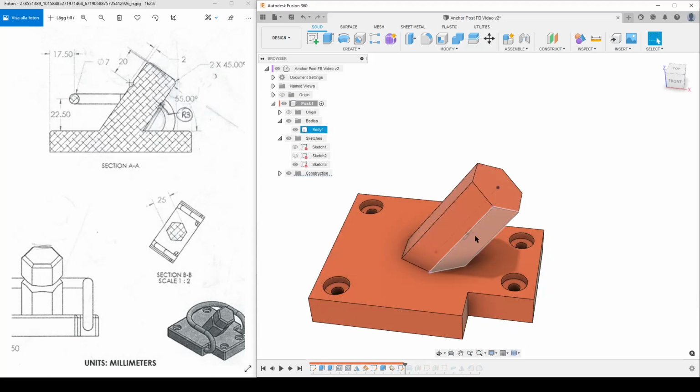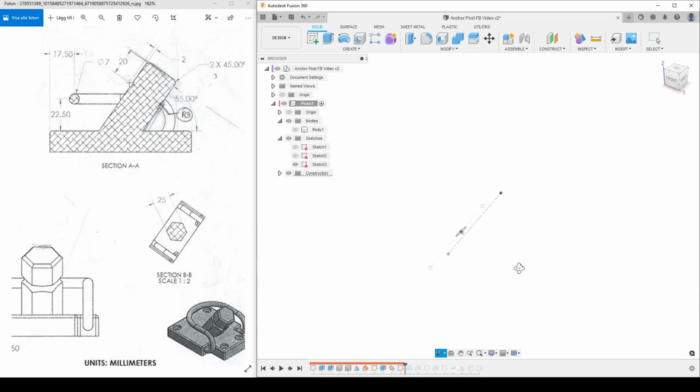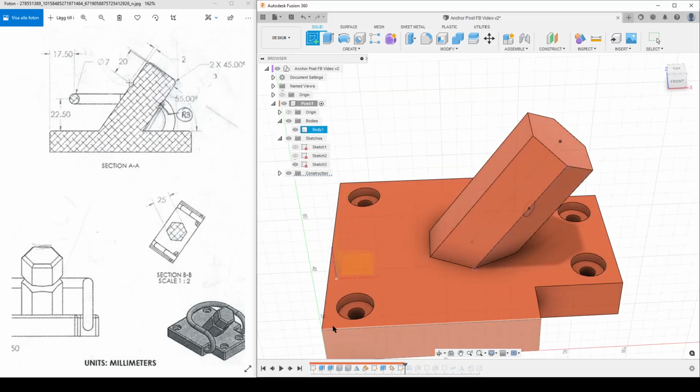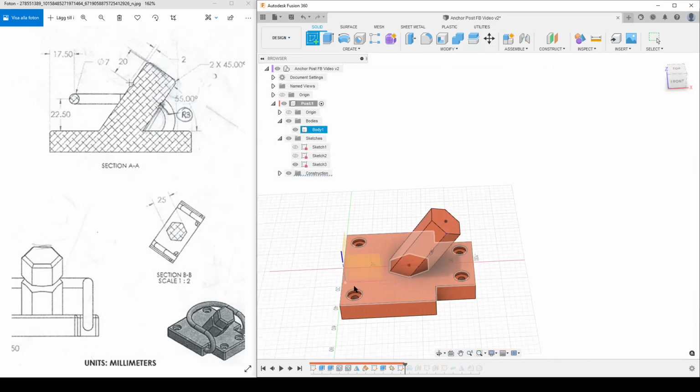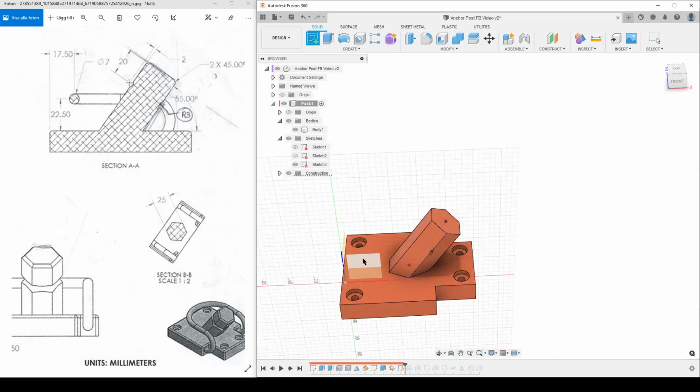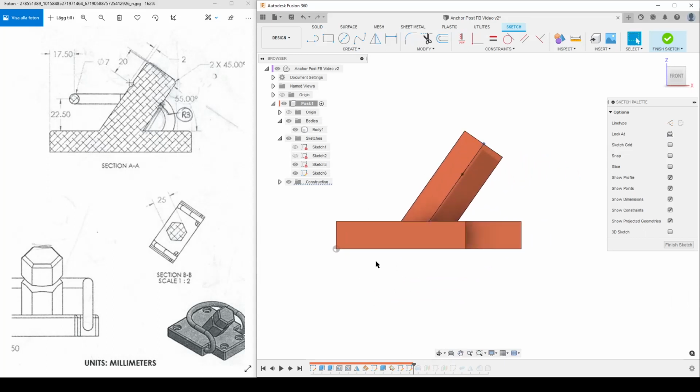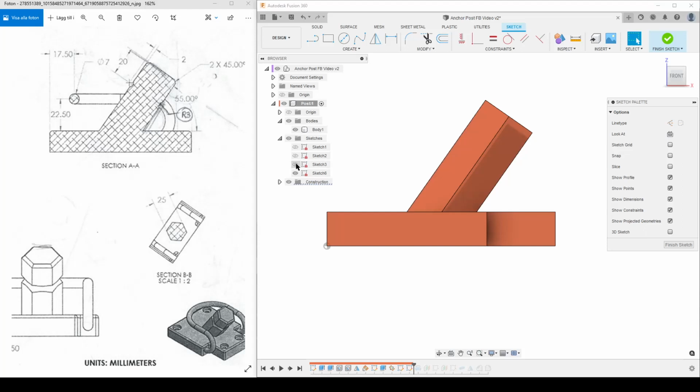So yes, I can go in and try to redefine sketch planes and stuff, but because this is a quite simple sketch, which is my intent when I do sketches, keep them simple, keep the bare minimum information needed in the sketch, I will make a new sketch. Let's turn the body in a useful direction, create new sketch. I'm going to create it on one of these origin planes here. Let's see if it makes it visible. Of course, these planes go straight through the body, as we made it symmetric to start with. Gonna hide the earlier sketch.